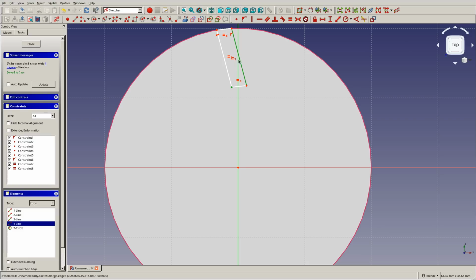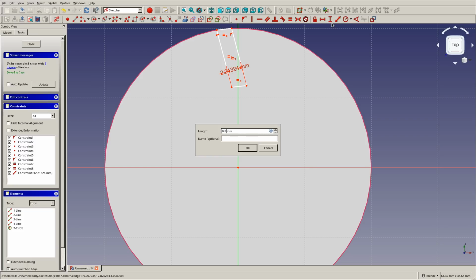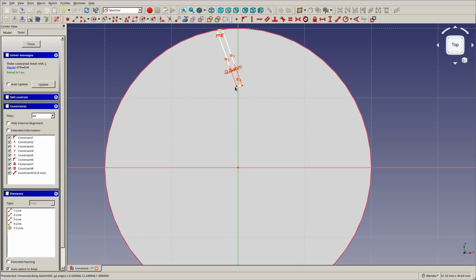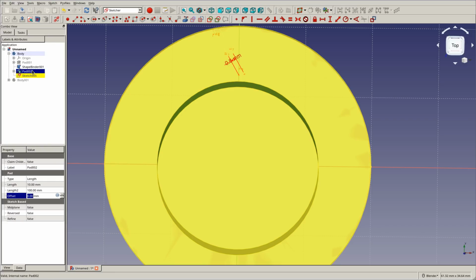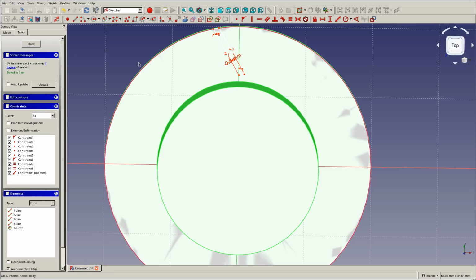So the thickness is a distance between this point and this line orthogonally. Let's say we want about 0.8 millimeters. This looks about all right. No, it's a bit too...